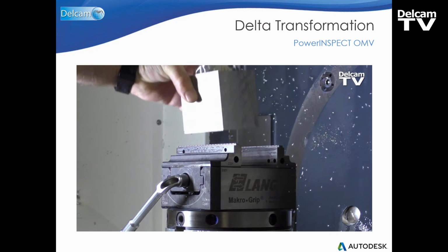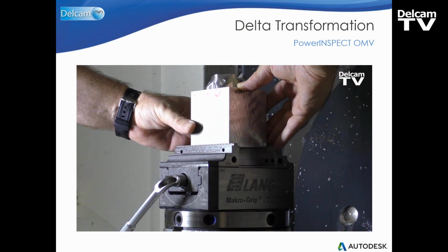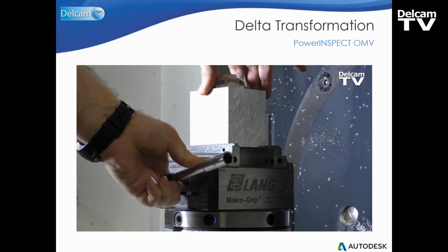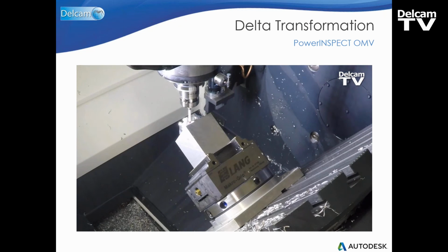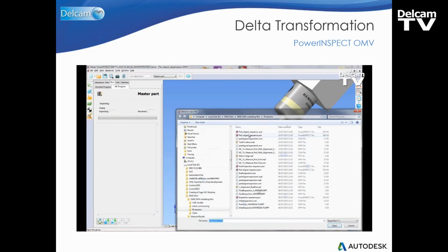Now on the machine, we insert and chuck our workpiece by hand so that it's roughly aligned with the correct axes, but we know that this isn't going to be good enough for further machining just yet. We'll then run our inspection routine using our on-machine probe in this case. The results from this inspection routine are saved on the control, and then we can read these straight back into PowerInspect. Okay, so now we're back in PowerInspect. We open up the results file,